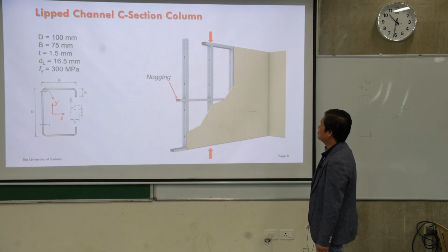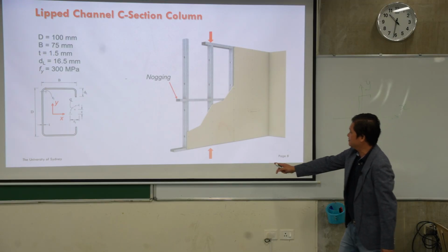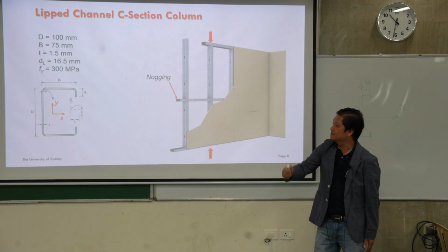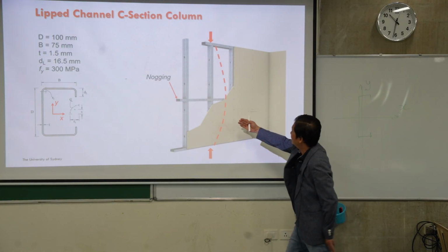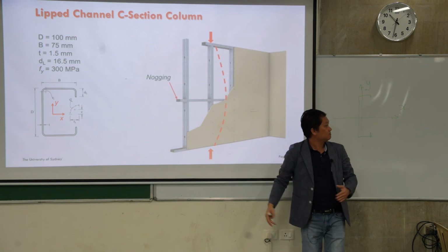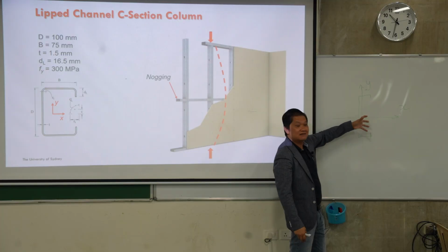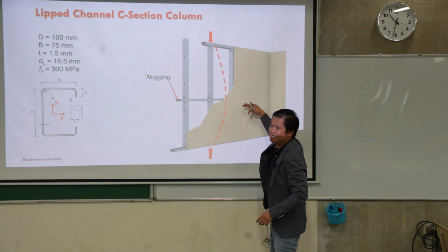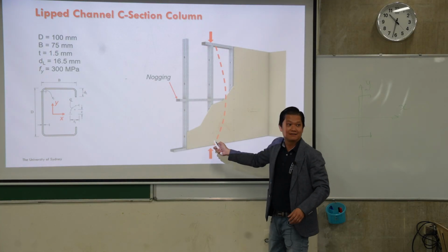When it buckles under compressive load, if you put the load on the top and the bottom here, then the column buckles in the red one. The red one is when the column buckles out of that plane. So it buckles this way, isn't it? So it's about the x-axis. We don't have anything to hold that, right? So it means that it's a half wavelength.